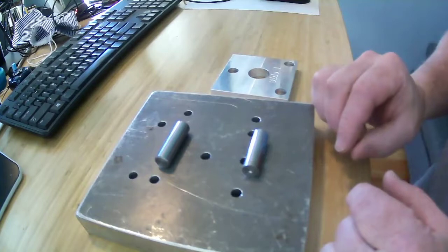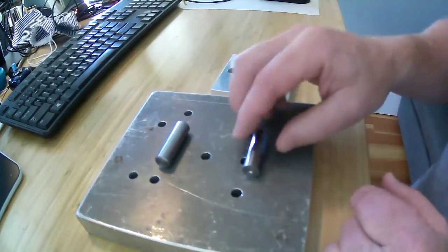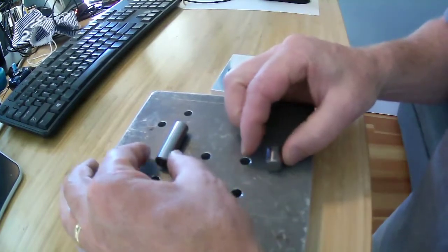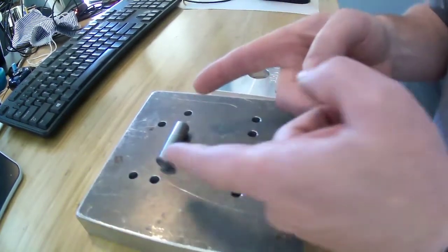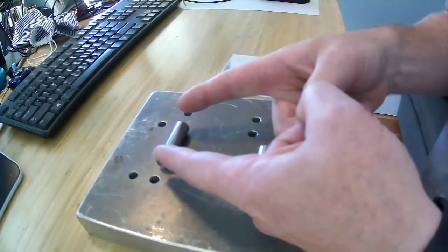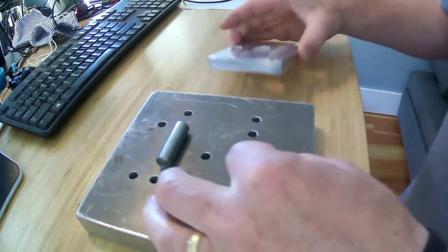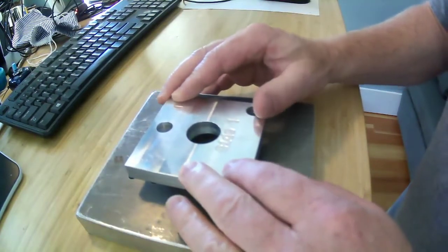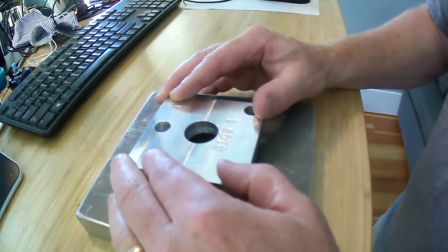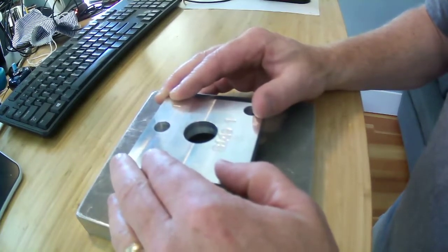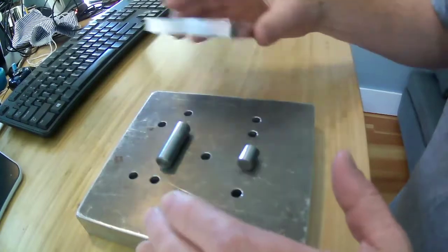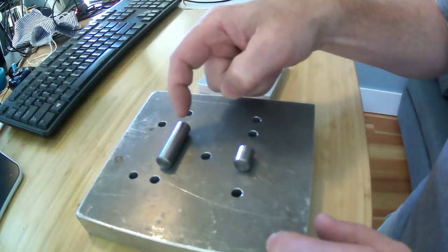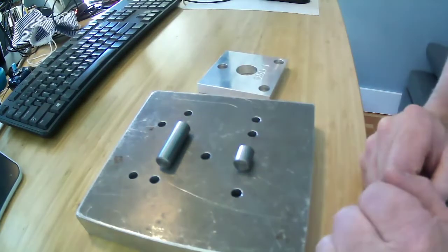Well, to increase determinism, one thing I could do is take this front dowel pin, and instead of making it long, I could make it really short. Instead of having a long potential contact length, I've reduced it even more. So I've made it more deterministic. Now when I put it on, maybe it rocks just a little bit, but it's much more deterministic. If I had to say where these two are contacting, I would say it's along this line somewhere and along that little tiny short line.